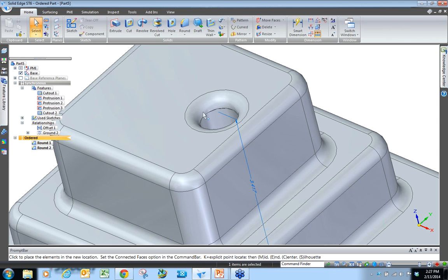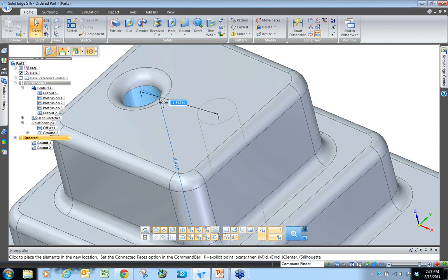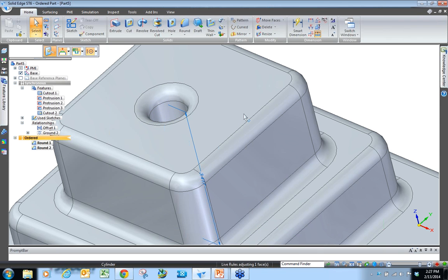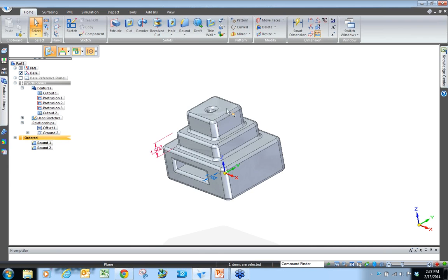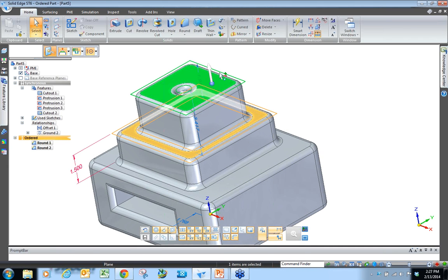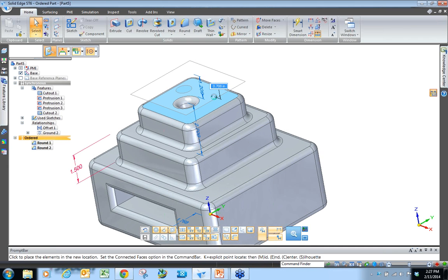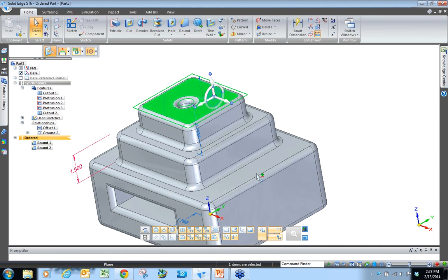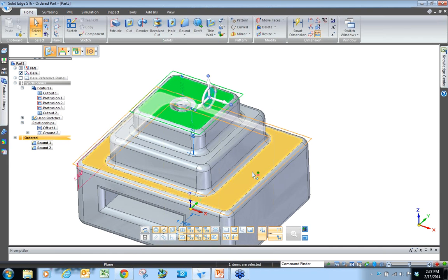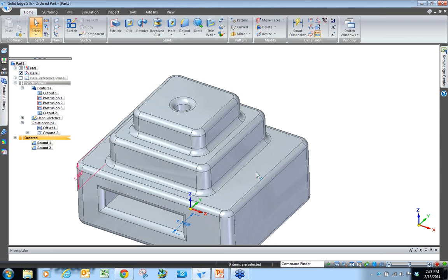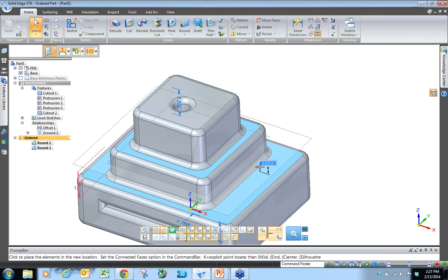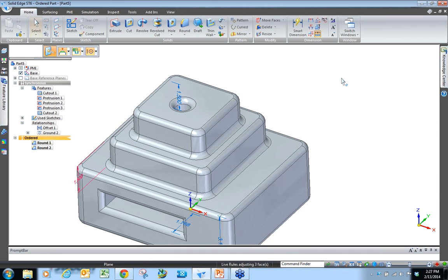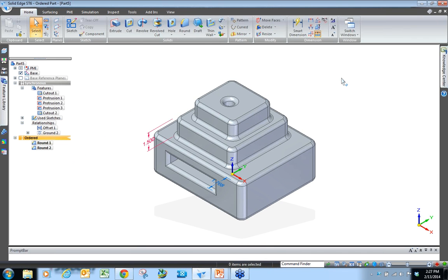Since I drew it in synchronous, I could still do my synchronous moves on it. If I wanted to change the height of the top block, the top tower, I can go ahead and readjust it synchronously. Even though I'm in the ordered environment, since all this was drawn within synchronous, I still have that ability, and I still have my steering wheel where I can direct the software to do things and direct my model and manipulate it the way I want.